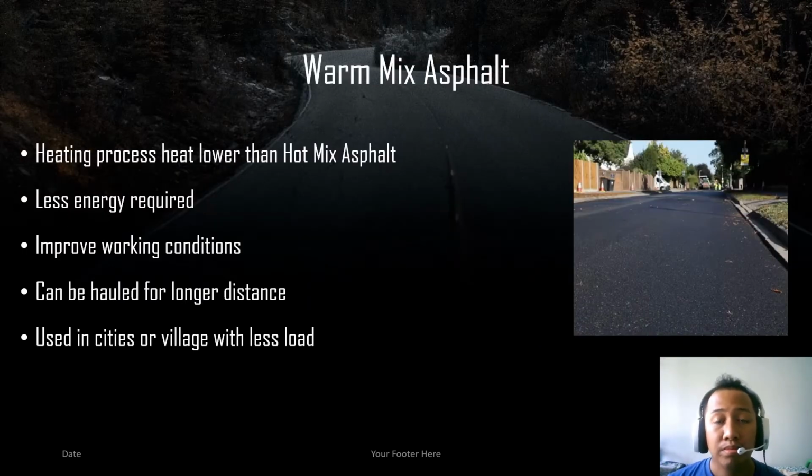Next is the warm mix asphalt. In this warm mix asphalt, the heating process for this mix is lower than the hot mix. Therefore, there's less consumption of fuel and energy due to the less heating required. Second, it improves the working conditions. In the process of pouring this mix, the laborers and the crews can have high workability due to the low temperature, different from the hot mix.